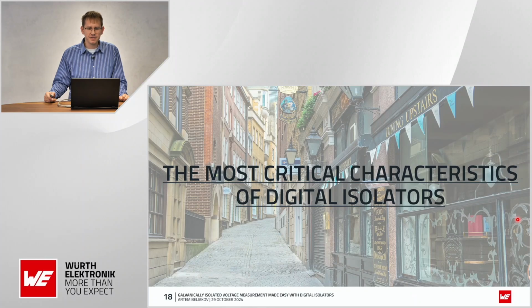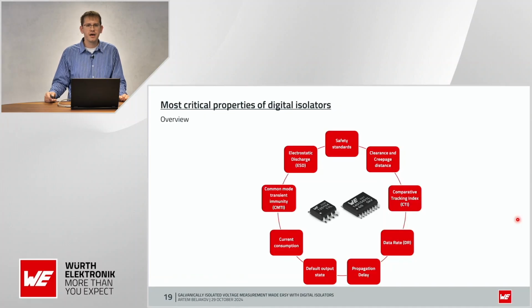Now that we have discussed the application of digital isolators, let's look at the most critical characteristics or properties of this product. These are the main properties of digital isolators: safety standards, clearance and creepage distance, comparative tracking index, data rate, propagation delay, default output state, current consumption, common mode transient immunity,